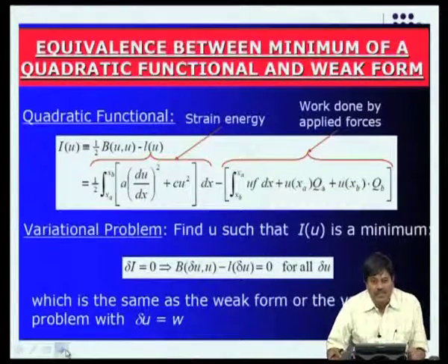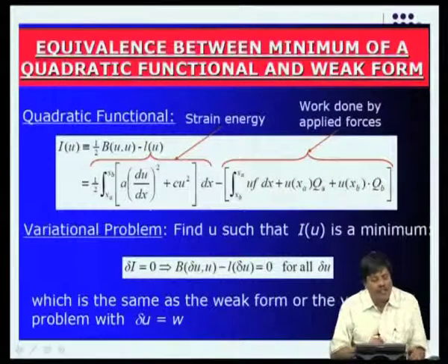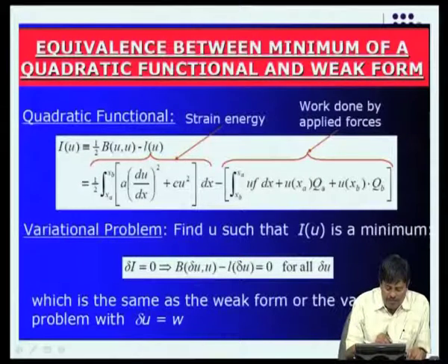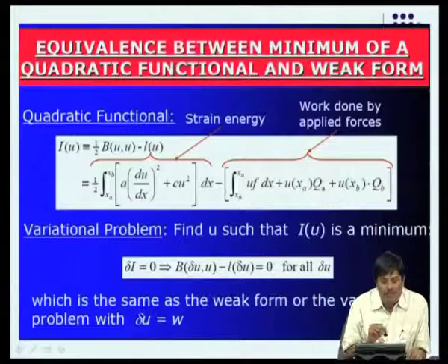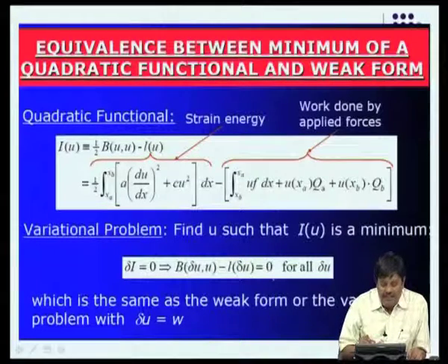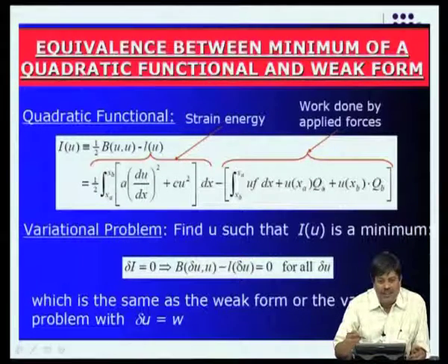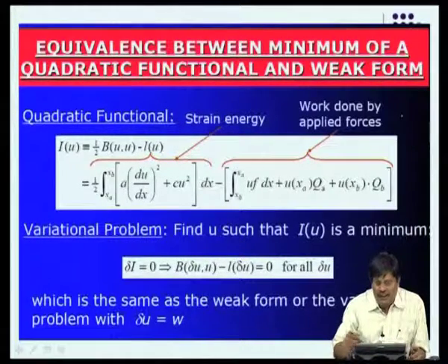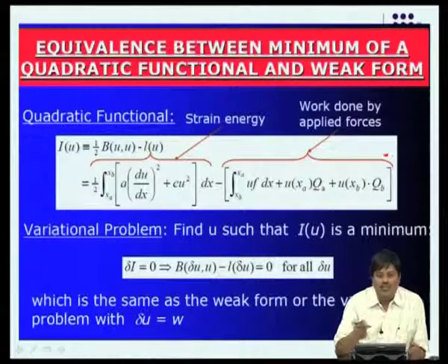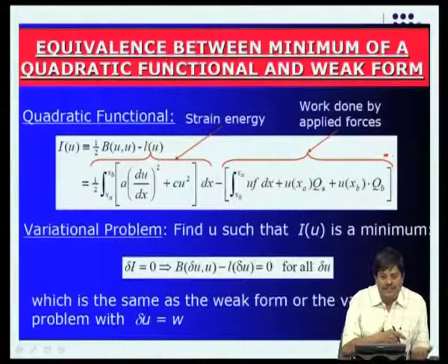Now, we revisit our theorem of minimum potential energy, where we wrote a functional which is called the energy functional, which is nothing but the inner product of u with u. That is, when W is replaced by u, we get this inner product. So, when we minimize this inner product, we get the weak form of the solution. So, here we can see how we adopt this for FEM and how this is related to the weighted residual technique.